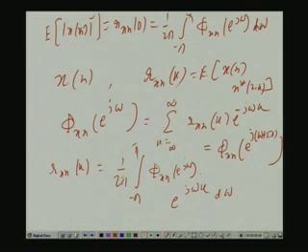d omega. So, you see phi xx e to the power j omega is such a function of omega, which when integrated from minus pi to pi, that integral, that is the area under this function phi xx from minus pi to pi, gives you average power. That is why it is called power spectral density, in the same way as phi xx j capital omega was called the power spectral density of the analog signal earlier. Same treatment. I am just giving the new definitions, that is all. Physical interpretations and all, they remain the same. Okay.